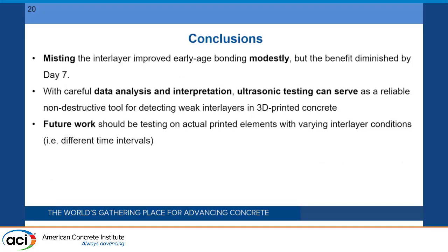And also, we found that missing the interlayer improved early age bonding modestly, but the benefit diminished by day 7. And lastly, I can say that with careful data analysis and interpretation, ultrasonic testing can be a reliable, non-destructive tool for detecting weak interlayers in 3D printed concrete.